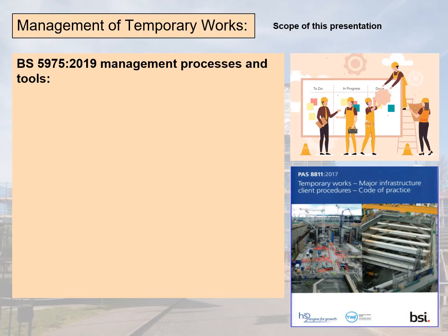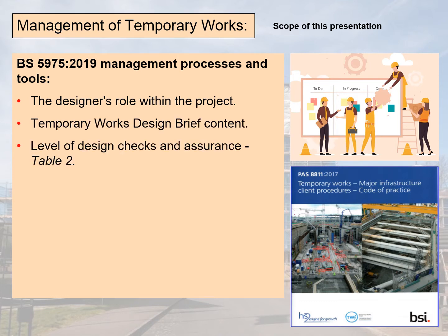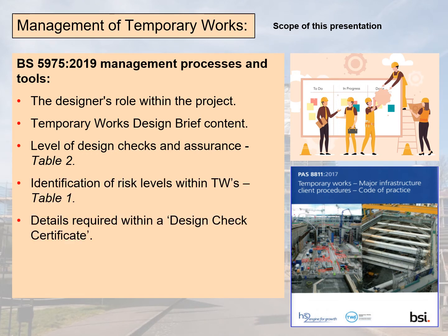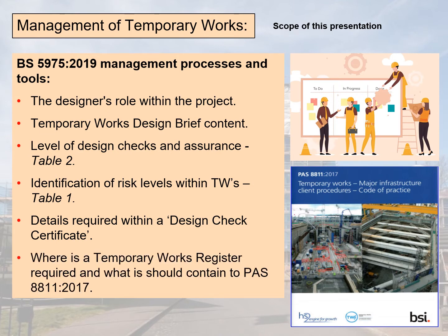Within temporary works, there's a number of management processes you should be implementing to help you manage and implement the temporary works on site. Within this presentation, we're going to concentrate on the following areas: the duties of the designers, the design brief, Table 2, and the categories for independent design checks, Table 1, the risk classifications for temporary works, the design check certificate, and the temporary works register.